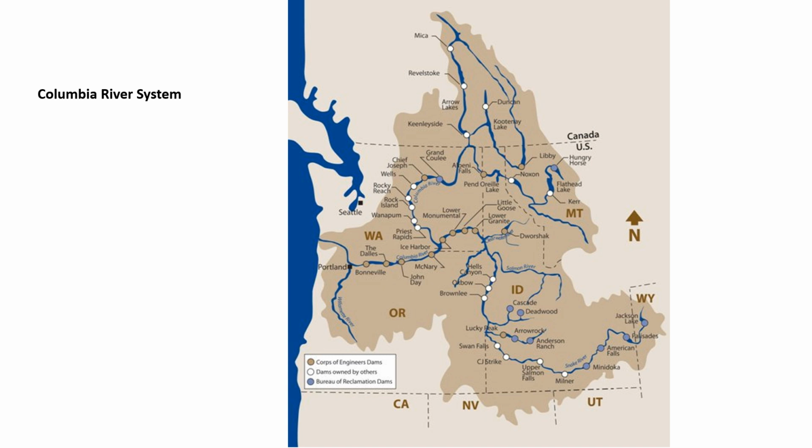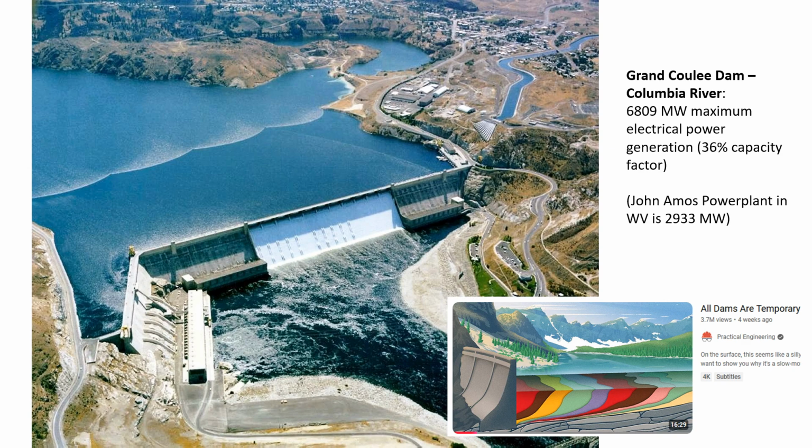And so there's soil in the water, and eventually the soil is going to be trapped behind the dam because the water velocity becomes much slower in the reservoir immediately upstream of the dam. When the velocity slows down, the soil particles settle downward. They don't have enough mixing energy to keep them suspended.